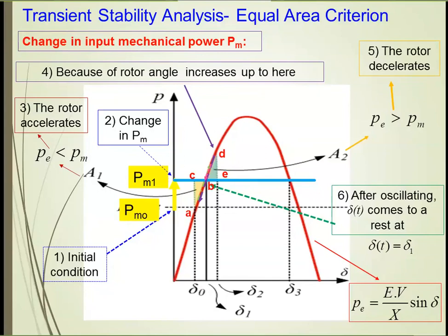If we are expecting that at this hour the electrical load is going to change, then we apply the generation change. Now here we use the term power dispatch. By power dispatch, it means that, let's say in a line you have 500 megawatt of power flow, and at another instant of time you are expecting an increased load. Then just before that instant of time you will change your 500 megawatt to 600 megawatt, or change your generation to 700 megawatt, and we call that the power dispatch problem.